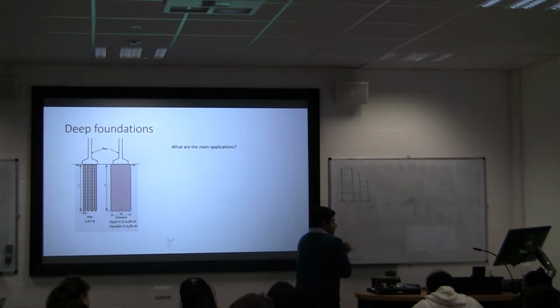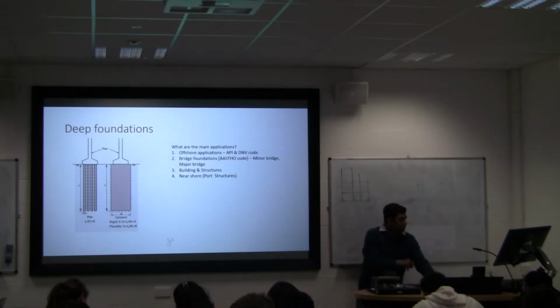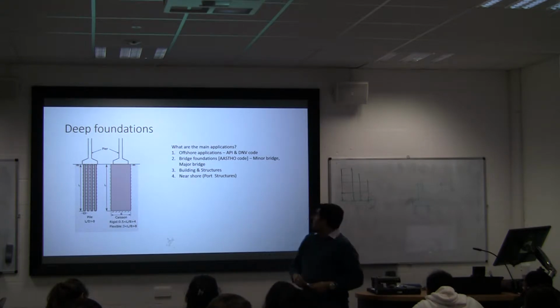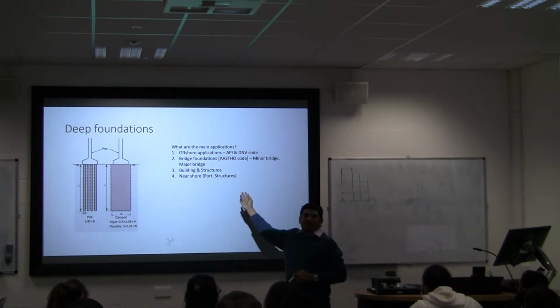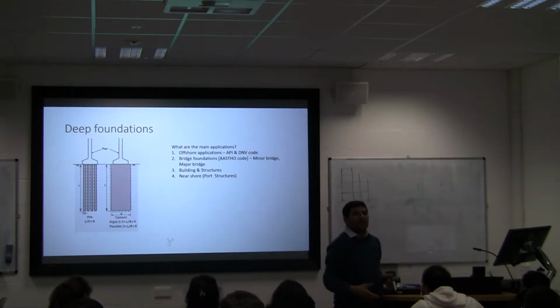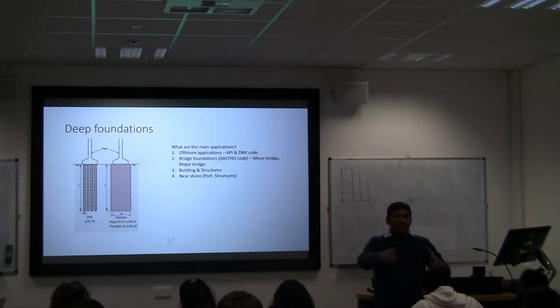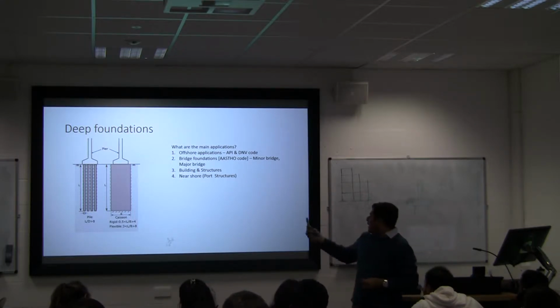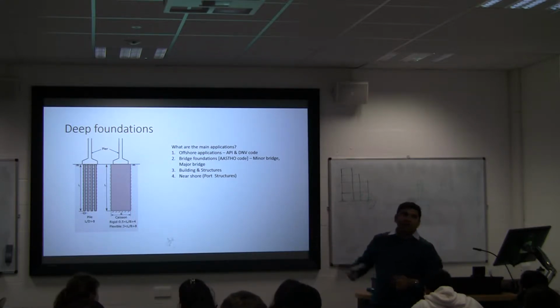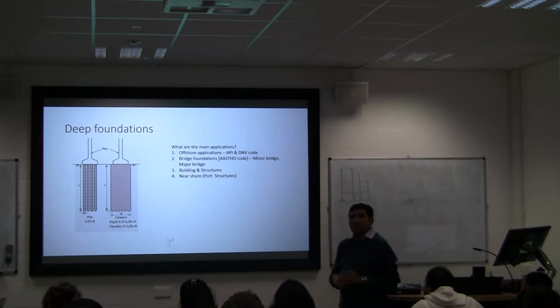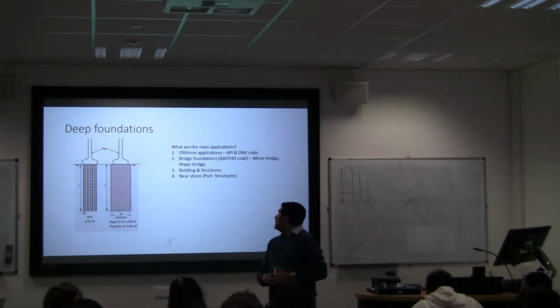Okay, that is right. So the applications are offshore, bridge foundations, port structures. If you have a port structure, you have to go for a pile foundation, isn't it? Because you really can't. So normally, underwater, you normally use a steel pile foundation. You hammer it down there, right? Because it's quite hard to have concrete there.